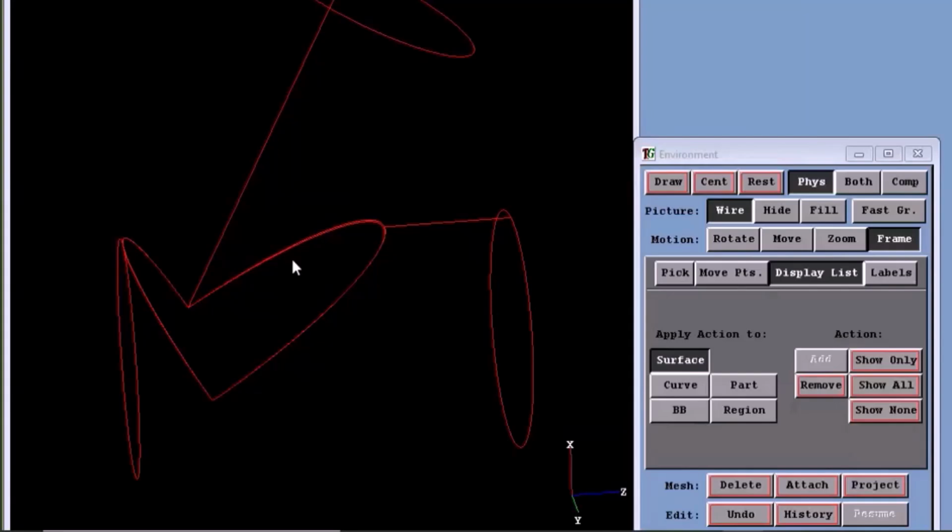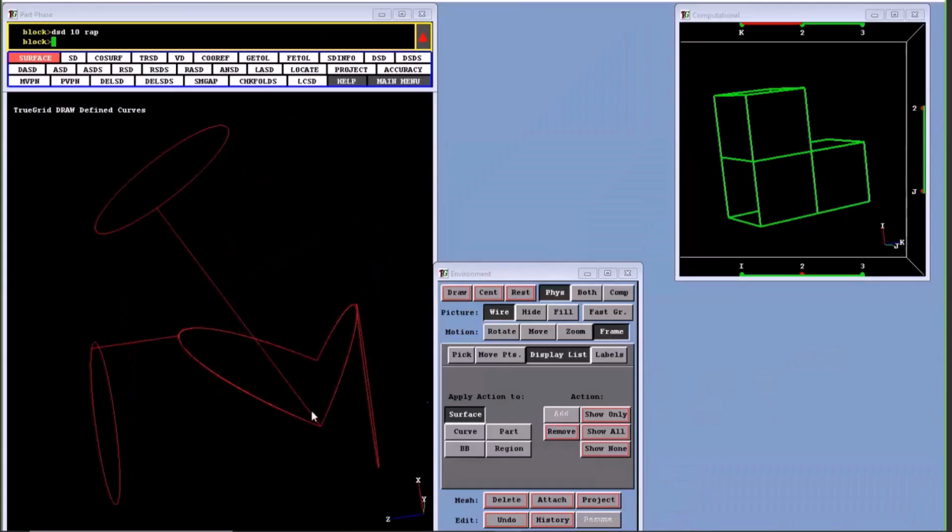They were having to mesh each one separately and try to glue them together, and it was a horrendous problem. We told them how to fix that by simply taking the composition of all 100 surfaces and treating it as one, and you project to the one even though there might be gaps between the surfaces or overlaps, and it worked beautifully. It took them just minutes after they had spent over 9 man-months trying to do it the hard way. So again, I want to emphasize just how significant the projection method is.